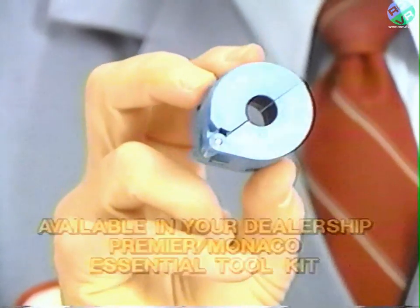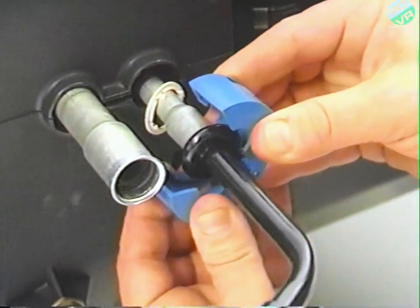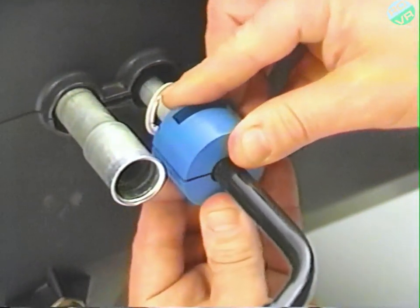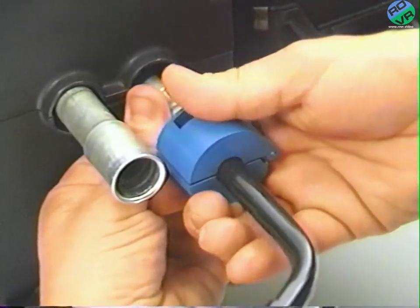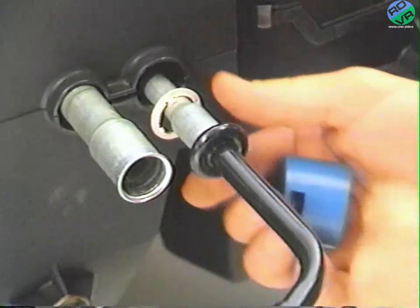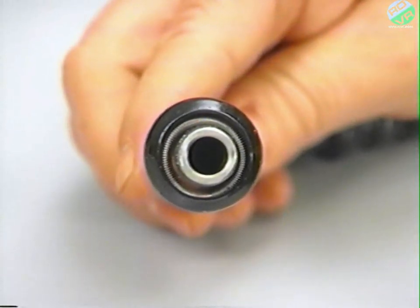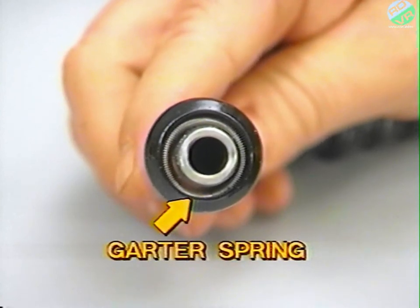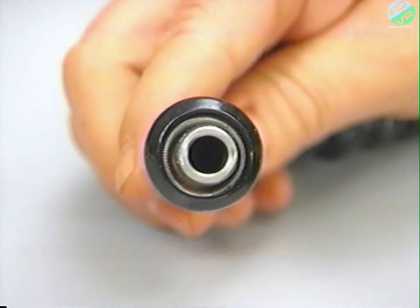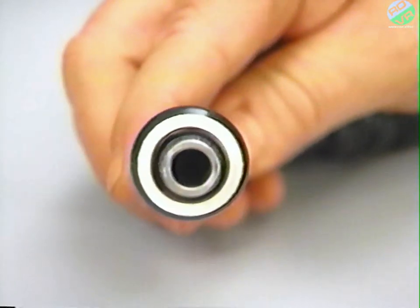To disconnect the coupling with refrigerant removed from the lines, fit the tool over the coupling with the spring release part of the tool over the female side of the coupling. Then push the tool into the cage opening to release the female fitting. Before reassembling the spring lock couplings, make sure the garter spring is in the cage of the male fitting. And if you decide to use the indicator ring, insert the tabs of the ring into the fitting.